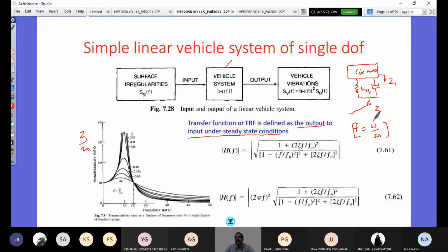It's because you give a road profile elevation and you get your response as acceleration, so your transfer function has to be multiplied with this omega squared factor, right? And you can see here the role of your damping at frequency ratio 1. That means f is close to or equal to f_n, the sprung mass frequency. You really require the help of a damper to attenuate this amplitude. If you do not, then it would be a severe problem, a breakdown of your vehicle.